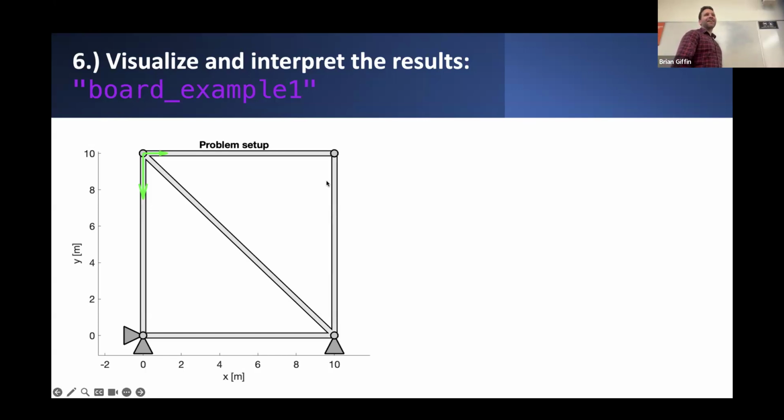So yeah, there's probably a few different ways you could rationalize what's going on here. But ultimately, if you took a look at this particular joint, you could do this just from basic statics, with a small method of joints approach. There are internal forces in each of these two members that are potentially pulling or pushing on this joint, but they're completely orthogonal.